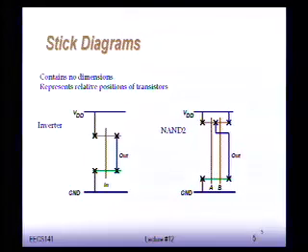So for instance, if you look on the left side of this graph, there is an inverter. And so what you can see is that this is the source of the NMOS. This is the drain of the NMOS, which is tied to the drain of the PMOS. And then this is the PMOS, so drain to source. The source of the PMOS is tied to VDD, okay?